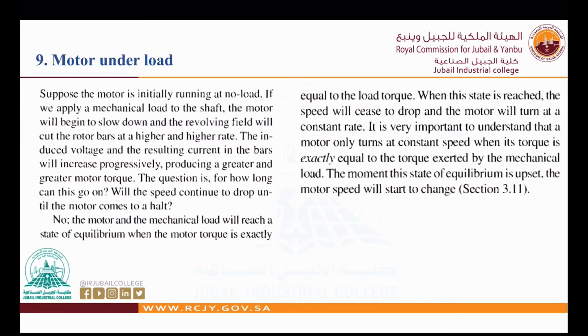Okay. Now, will the speed continue to drop until the motor comes to a stop? No. The motor and the mechanical load will reach a state of equilibrium. They will be equal when the motor torque is exactly equal to the load torque. So we have two torques here: the motor torque, which is the induced torque, and the load torque, which is on the shaft.